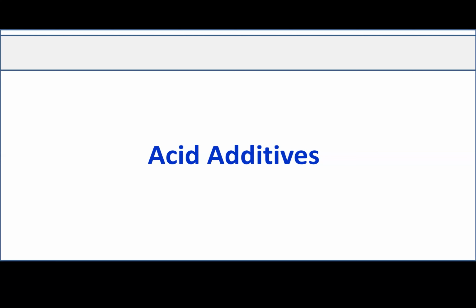And we are talking about a local area, not reservoir scale. We're talking about the local area where the acid reacts. That's how it's happening, because you are dissolving and creating voids or vugs. That will be reflected in the porosity increase, and that will improve the permeability of the formation.